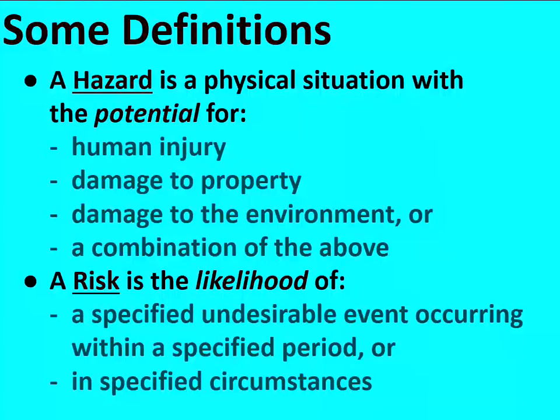When you do hazard analysis, you should come out with a number which says the risk of this hazard happening is once a month, or once every 100 years, or once every 1,000 years. Once you get into analysis, you're really talking about actual quantitative factors, which have got numbers associated with them.